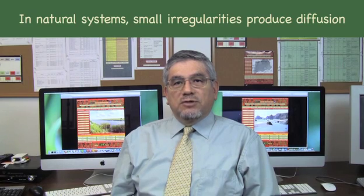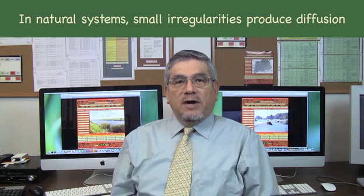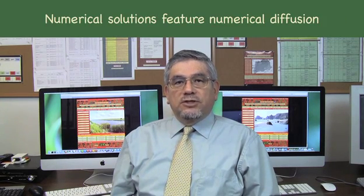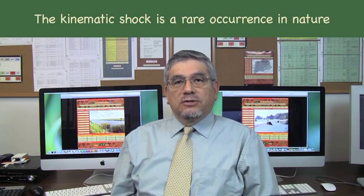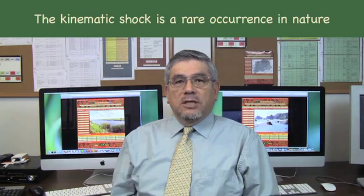In natural systems, small irregularities produce diffusion, which has the effect of counteracting the steepening. Numerical solutions feature numerical diffusion, which also arrests the steepening. Analytical solutions have no diffusion. Therefore, an analytical solution of the kinematic wave is poised to eventually develop the shock. Natural systems have intrinsic built-in irregularities. Thus, the kinematic shock is a rare occurrence in nature.